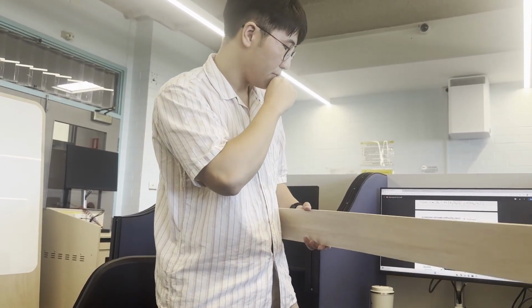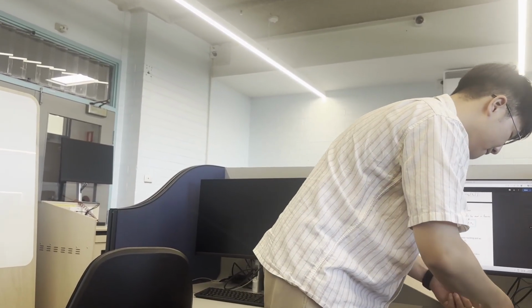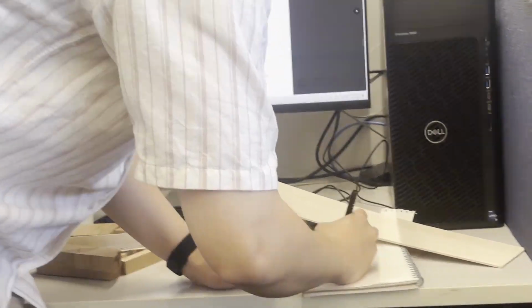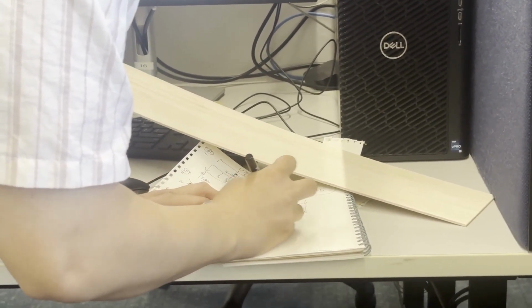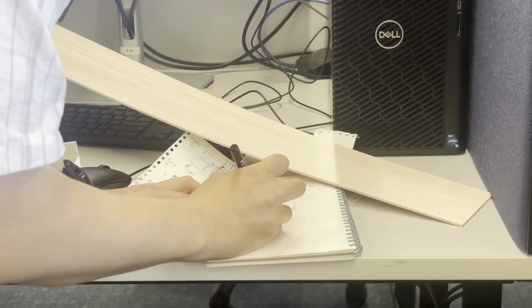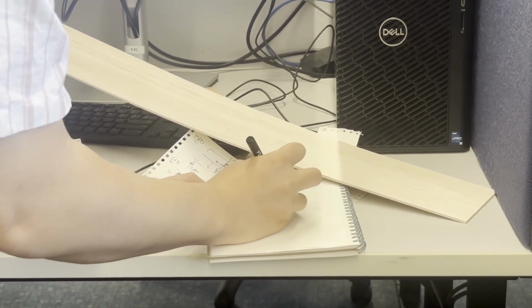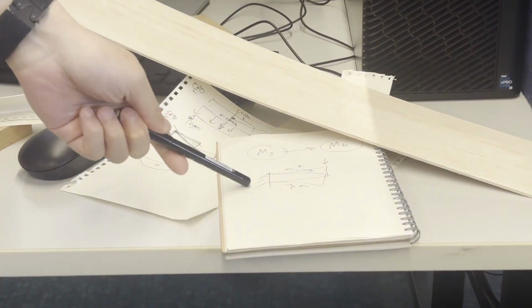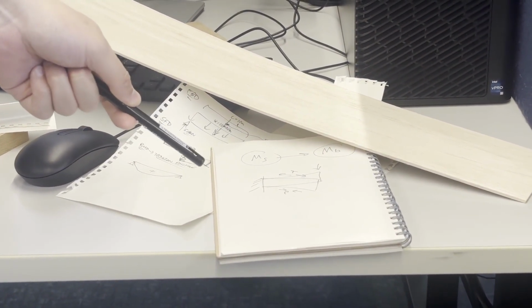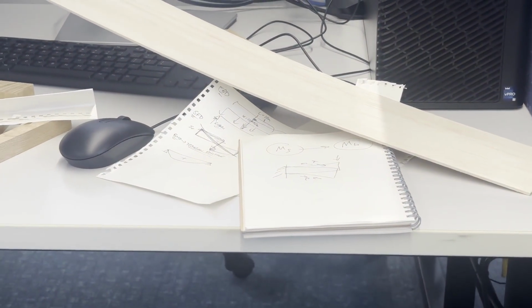But for a cantilever, okay, and you apply a downwards load to it, the compression side's actually at the bottom, and the tension side's actually at the top, okay? Because you can just see how it deflects is different, okay? So the bottom's actually in compression, so it's flipped, as opposed to a simply supported beam.